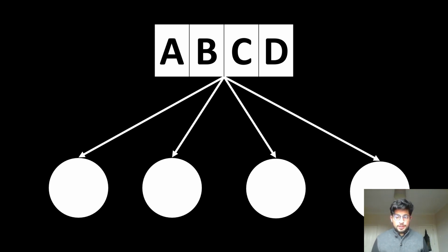In the first one, it's referred as homogeneous, and in this case, what you do is that you have a single genome or a single controller for all of your robots in your experiment in swarm robotics. So basically what you do is you take a copy of the genome and you put it in all the robots. And all the robots are gonna share the same genome.